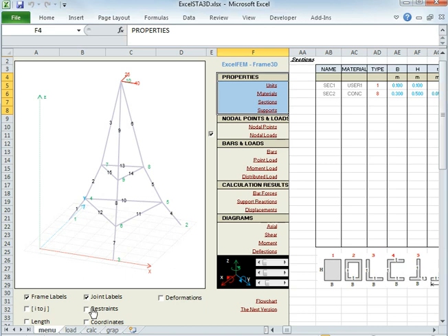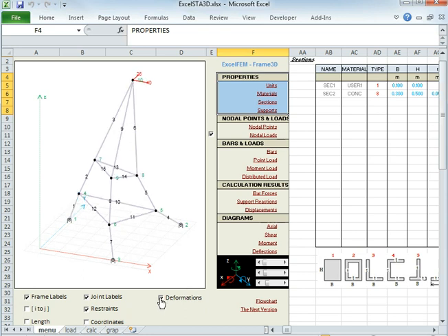And we can hold this frame down using restraints. So I'm going to hold this down at the bottom of the tower structure, and they're going to be pin supports there. And at the top of the tower I'm applying some loads, and once we've applied some loads we can see some structural deformation. So that's how the structure is going to deform.